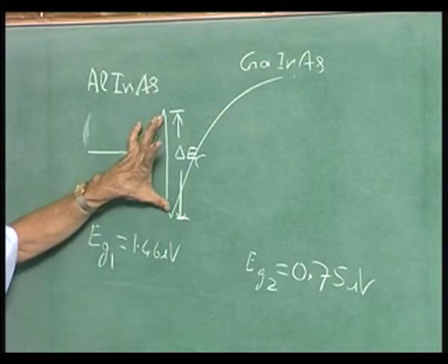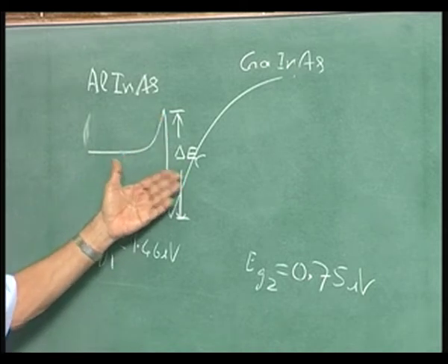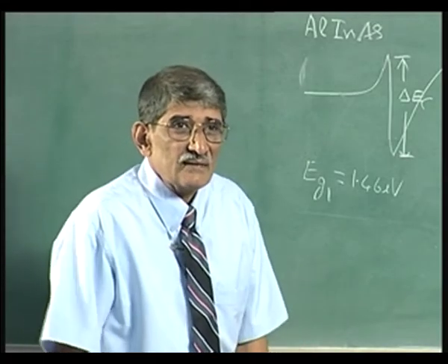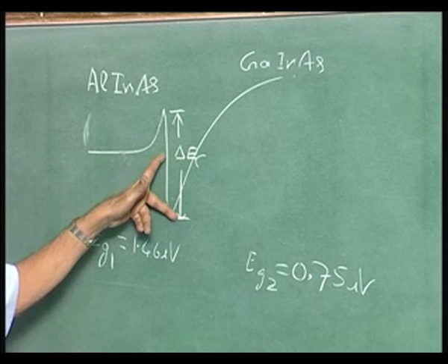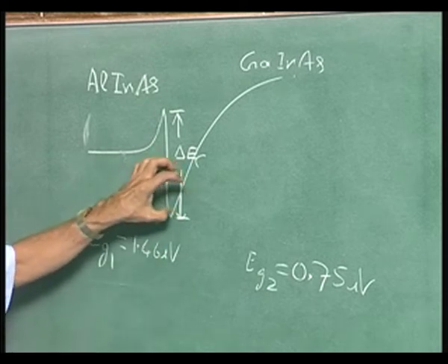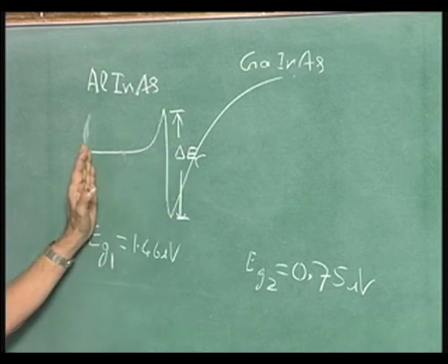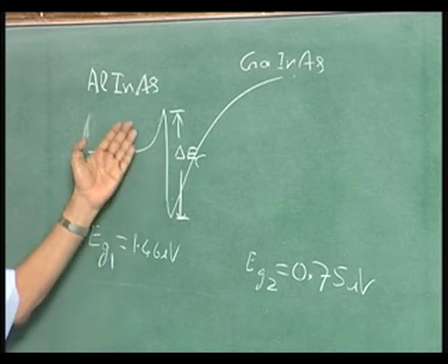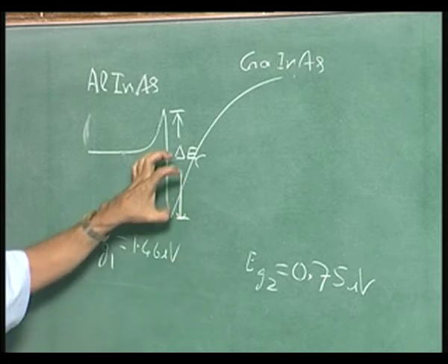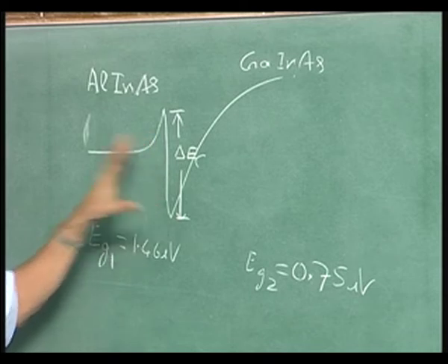If this is higher, the quantum well is deeper, more electrons are held there, they are locked up there more. That means the maximum current or the maximum transconductance that you get as a result will be higher if the delta EC is higher, particularly maximum current, because of how many electrons you can hold here without opening up conduction in this region. That is what is implied by that. We discussed it in the previous lecture. So, delta EC determines the number of electrons and the maximum current.